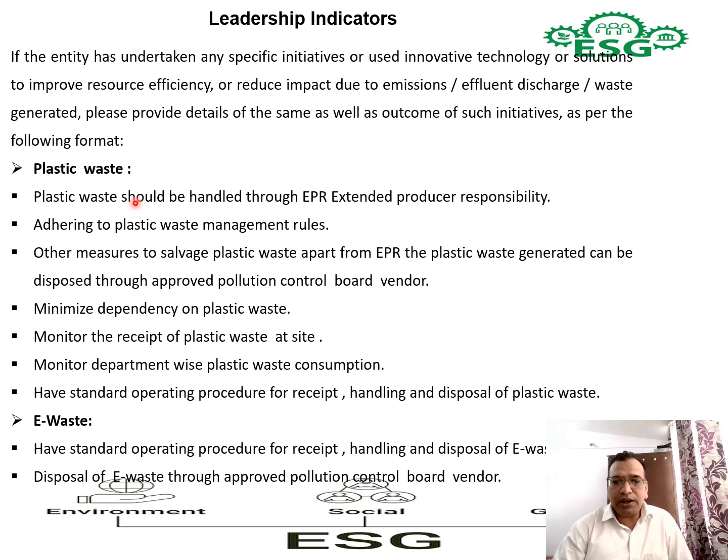But individually, for the waste which we have discussed, we will see how initiatives can be taken or how the waste has to be handled. So first is the plastic waste. Plastic waste should be handled through EPR, that is extended producer responsibility. If the company is not yet registered under EPR, it has to be registered if it comes under the purview of the plastic waste management handling rules.